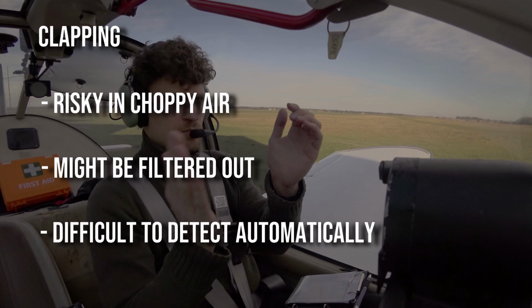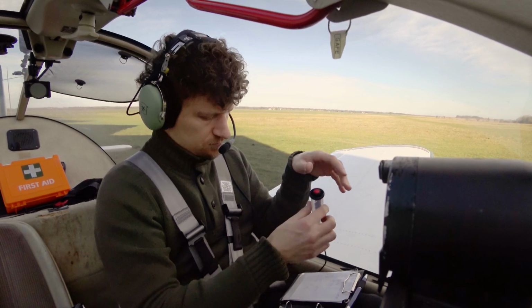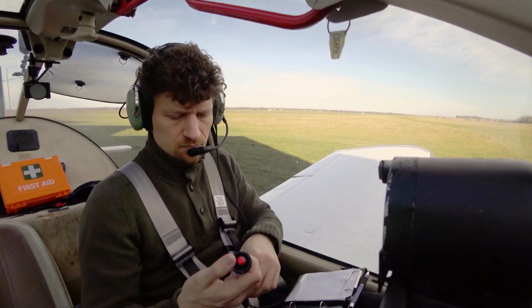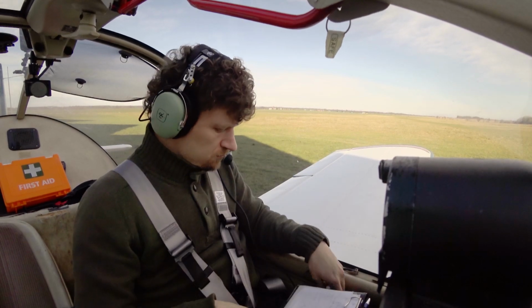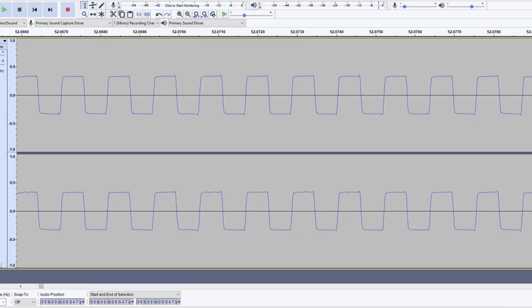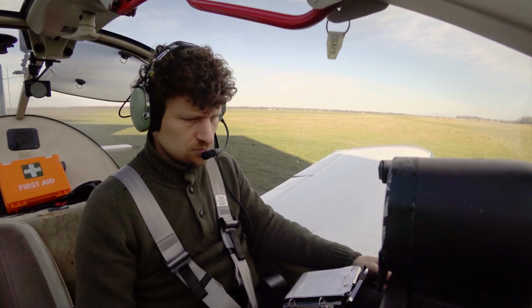The solution would be to build a small device that sends an easily distinguishable tone directly to the voice recorder. Such a tone should be a square wave, as this is the easiest signal to detect in a simple program, and since it is recorded directly, there is no risk of any noise interfering with it.